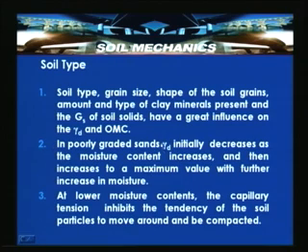In poorly graded sands, the dry unit weight initially decreases as the moisture content increases and then increases to a maximum value with further increase in moisture content. Basically, sands have a different phenomenon from cohesive soils, which is explained in the form of the bulking phenomenon of soils. In moist conditions the volume appears to be very high, because there will be some capillary forces between the grains, and these induce some apparent cohesion between the particles and hinder the particles from coming closer. In the process, the density decreases, and after adding a certain amount of water, the films surrounding the particles get washed out, and the particles can move to closer positions.